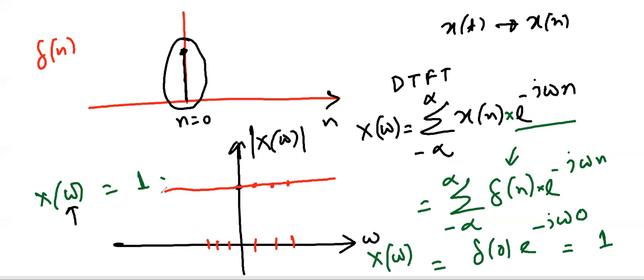How long can we continue this? What would be the limit? Of course, the limit is up to pi, and on the negative side, minus pi, because that is our range of view. To restrict the aliasing, we need to restrict our value of omega up to pi.